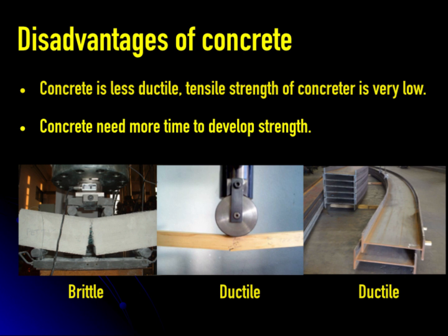However, concrete also has disadvantages. First, concrete is a brittle material, and its major weakness lies in its low tensile strength. This is why steel reinforcement is necessary in most concrete structures to improve tensile capacity. Concrete also requires a long curing time, typically 28 days, to reach its full strength.